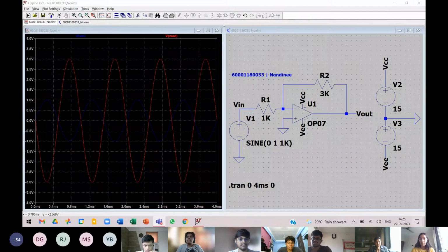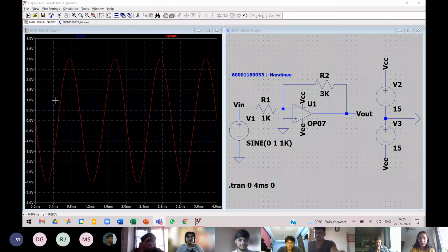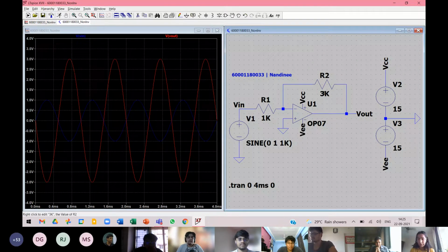file. All right, so this is your inverting amplifier practical. This is how you will be doing it. And for different gains, you will be changing the resistor values. And to actually notice the clipping at the saturation level, you will be changing the R2 value, or you can also change the voltage given, right? So I will be showing you guys that.